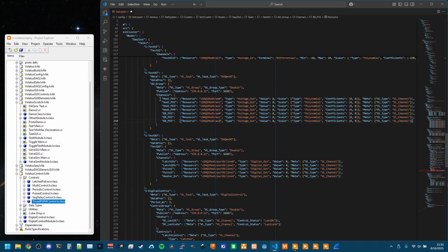Now, I'm basically using these as software variables. So I do have the scaling set to just always set it to 0. So no matter what I want the process value range to be, let's say we're doing temperature and we're going to a couple hundred degrees, or this bang bang might be a couple thousand if we're pressurizing things, potentially. But these voltage outputs do have limits, typically -10 to 10. So we're just changing it always to multiply by 0, so that we don't get any DAQmx errors when we're trying to send arbitrarily large values. And I'm lazy and just ignoring the scaling.